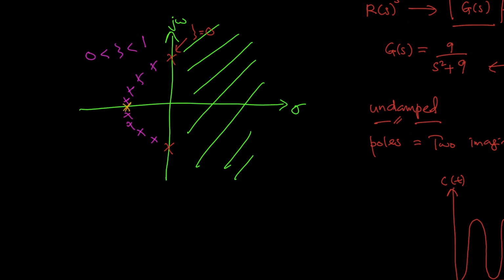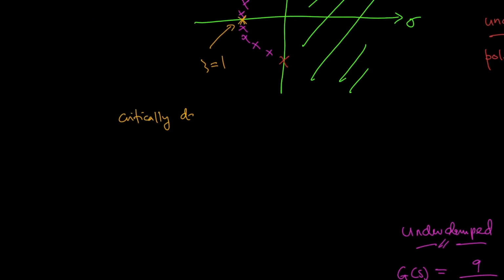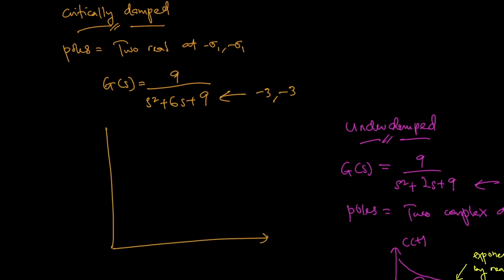For a critically damped system, the value of zeta is equal to 1. The function has a pole at the origin that comes from the unit step input and two multiple real poles that come from the system. The input pole at the origin generates the constant forced response, and the two poles on the real axis generate a natural response consisting of an exponential and an exponential multiplied by time, where the exponential frequency is equal to the location of the real poles. Critically damped responses are the fastest possible without the overshoot that is characteristic of the underdamped response.